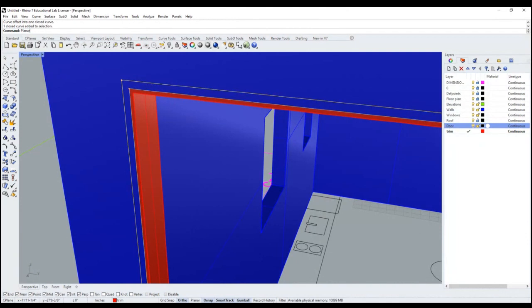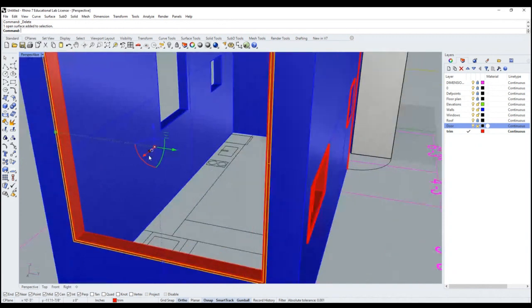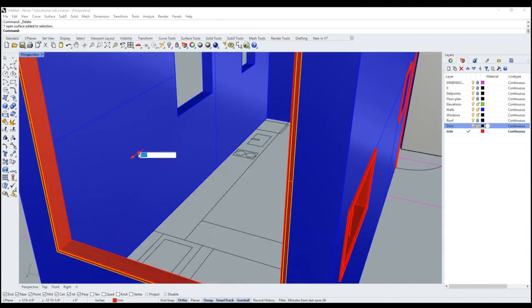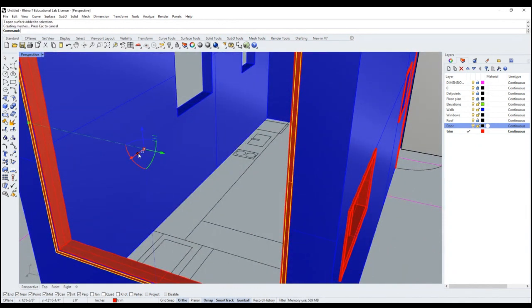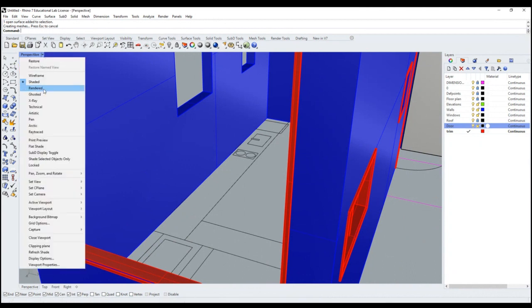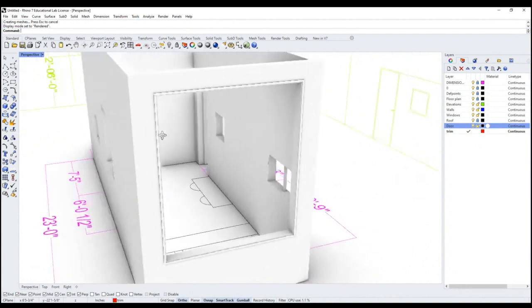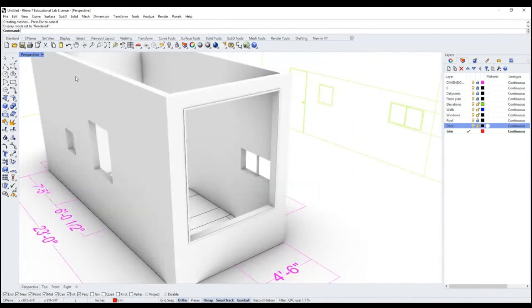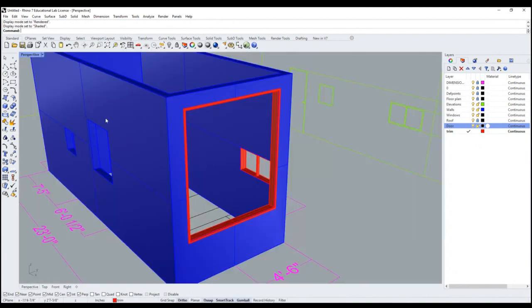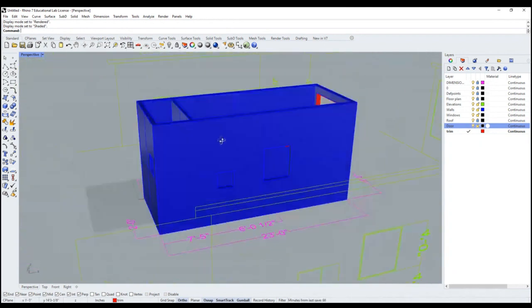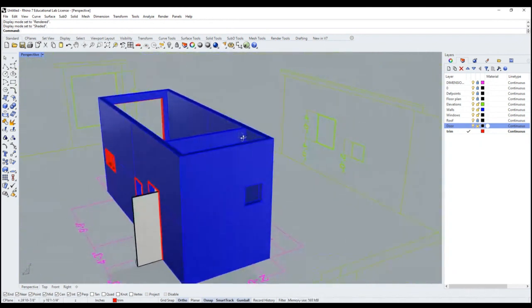Select both, planar surface, delete the curve, and red ball in the middle of the arrow will extrude us 1/2 inch out, and it'll give us this window here. Alrighty, so we have 3 more windows to go.